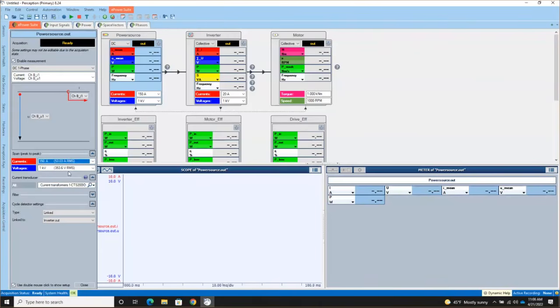So I'll select that 150. On the voltage side, I don't need a transducer in front of my channel because these voltage channels support up to plus minus 1500 volts directly. I don't expect to be measuring above a 500 volt peak for my DC power input, so I'm just going to select that 1 kV span and leave it there.